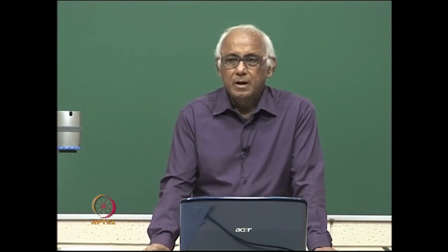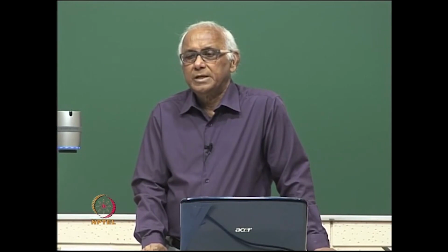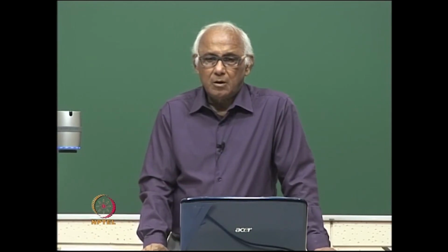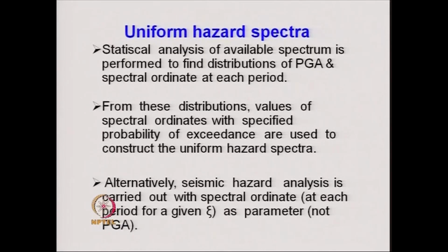And once we get these probability density functions or the CDF, cumulative distribution function, then from these distributions, the values of the spectral ordinates with specified probability of exceedance are used to construct the uniform hazard spectrum.